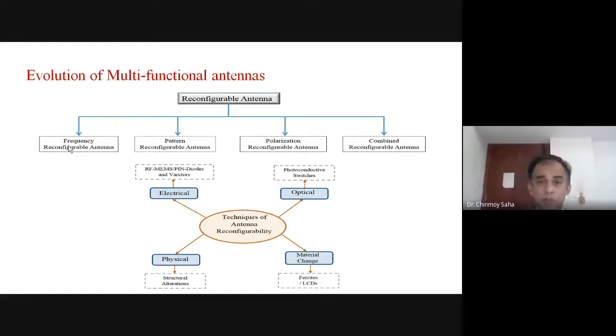The multifunctional antenna is maybe somewhat close to these reconfigurations, but the idea or the genesis is different. Here the requirement is to design antennas considering the functional feature. Sometimes I want the antenna to be wideband, sometimes I want the antenna to be notched wideband, and sometimes I want the same antenna to be acting as a narrowband. Not only that, that narrowband operational frequency should be tunable at different frequencies. This is the combined and compact requirement of such an antenna system.